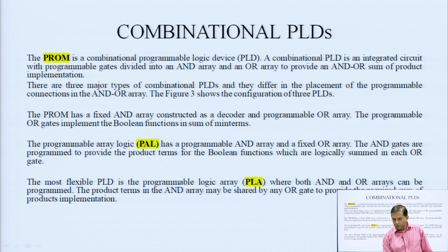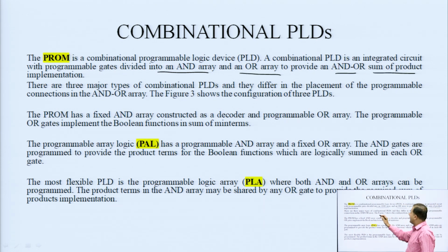Next, we will discuss combinational PLDs. The PROM is a combinational programmable logic device, PLD. A combinational PLD is an integrated circuit with programmable gates divided into an AND array and an OR array to provide an AND-OR sum of products implementation.